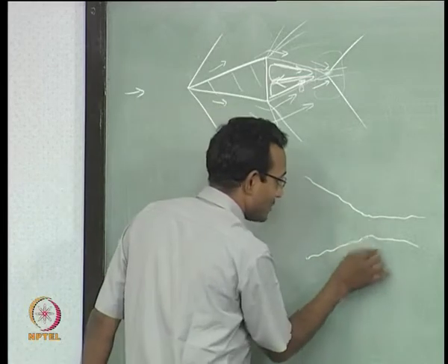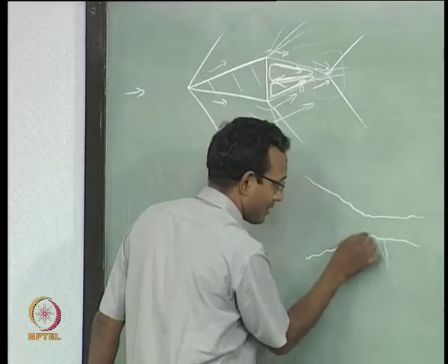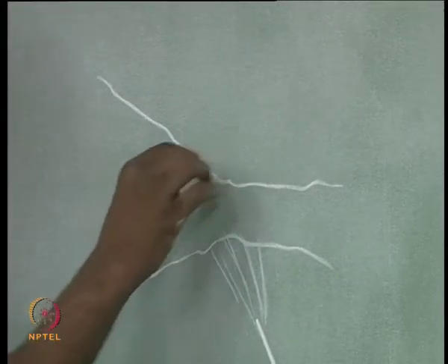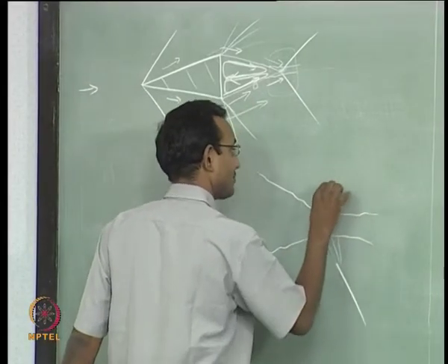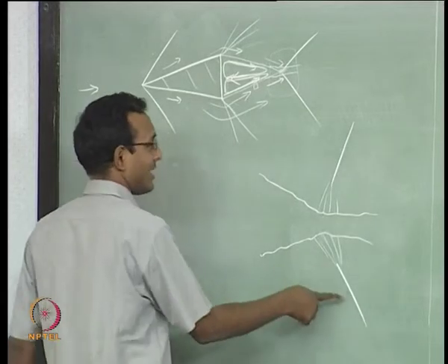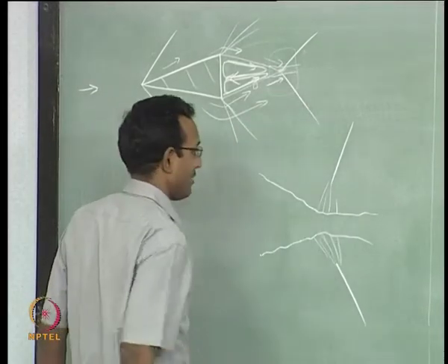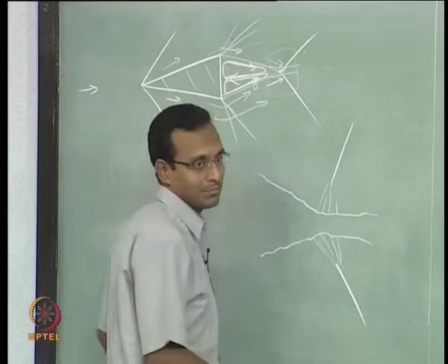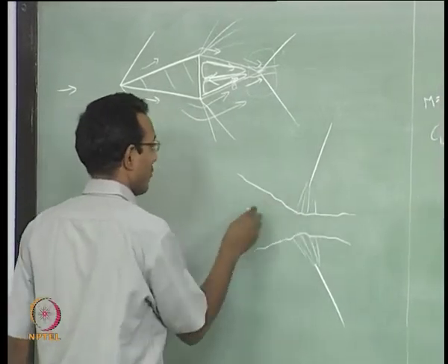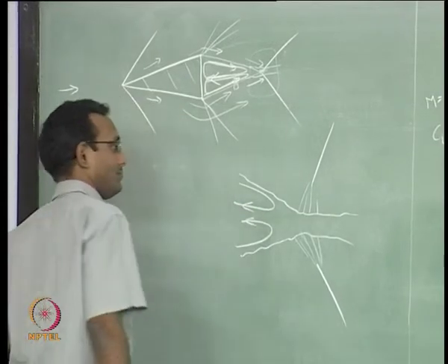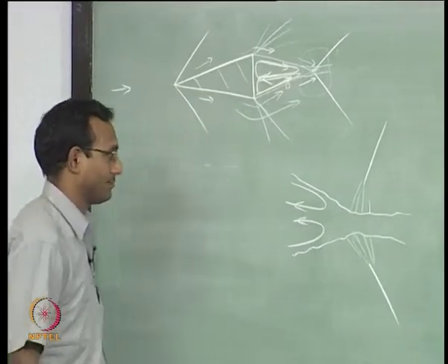So, you are going to have a bunch of waves together, compression waves coming together to form that shock now. This is what will happen there. But this final angle will be the same as what you have drawn with your simple case. Okay, the final oblique shock angle will be the same. This is the kind of flow field you will get, and here is your recirculation zone. This is what you will get.